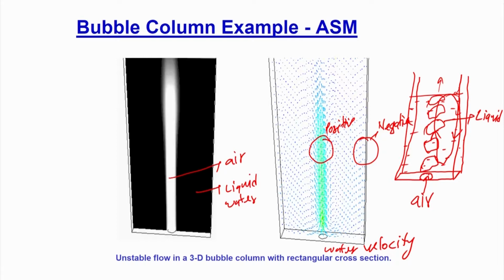Okay. So, these are the simulations. This simulation has already been shown in the literature. We have just repeated the simulation to see that you are able to get the same profile. This is a standard way to solve the bubble column. So, if the discrete phase volume fraction is very low, say less than 5% or 10%, you can use this model to get the information, and we are able to get it in a very quick, or relatively faster, way compared to the models which we will discuss hereafter.